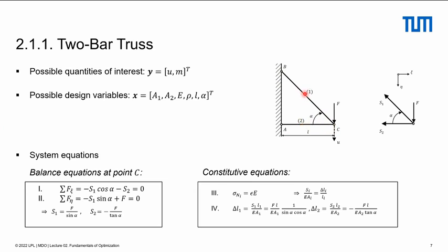consisting of 2 rods with joints attached to a wall, and there is a vertical load applied to it. For those from aerospace, I think there was only one person, but also for mechanical engineers, it may be more exciting to think of a bipod. Satellite structures are sometimes supported by bipods, and this is the mechanics that's relevant for them. We want to do something with the displacement of that thing, and I can tell you already, we want to build a lightweight structure that is stiff, okay? And we want to find an ideal lightweight structure by using an optimization framework.